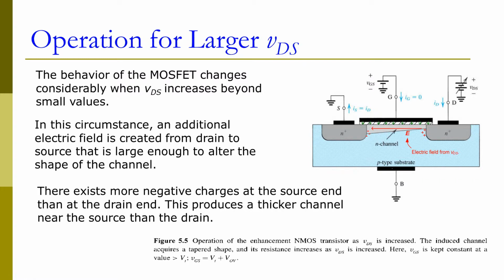smaller. The reason for this is that with a larger drain voltage here, the PN junction at the drain side is reverse biased. If we have an increased drain voltage, we are going to form a wider PN junction, right? So the depletion region becomes wider, which also means we are going to form a lot of negative bound charges. These bound negative charges will push away the free mobile electron charge, which will narrow the channel here.